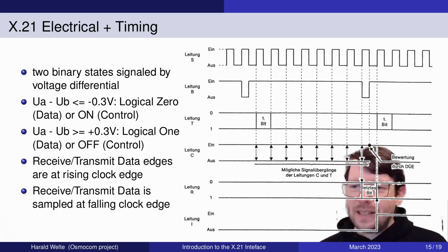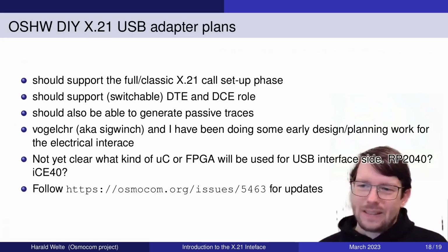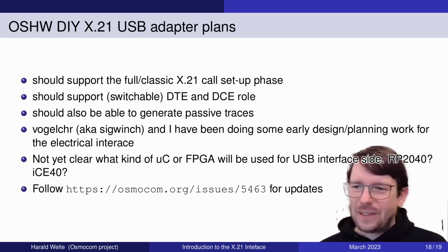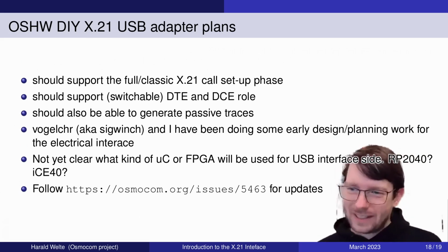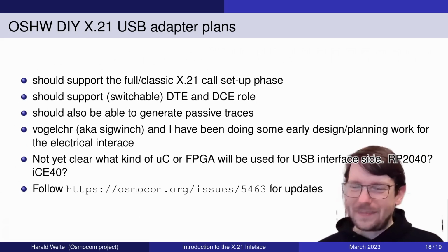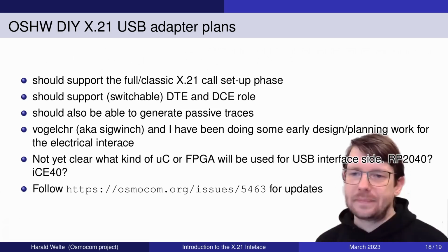Yeah, I mean, to me, if I find some explanation, it's fine. But if not, it's also fine. In the end, we just have to implement it like it's in the spec, and it's a negation. Yeah, whether it's left or right, okay. Still, I think A and B is the other way around than RS 485 from the polarity. But I think one has to just try it out to be sure with all the different definitions.